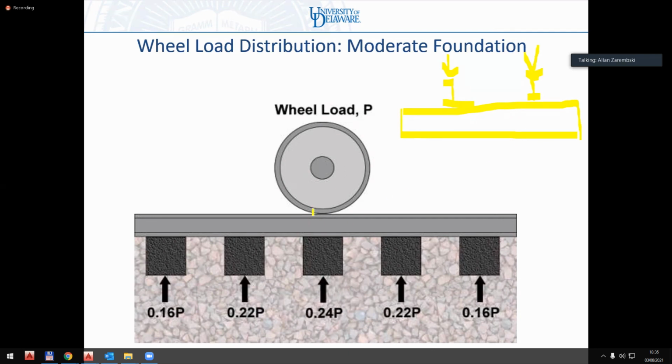But we do this analysis independently because each rail is subject only to a wheel load. So if I want to calculate the stresses in my rail, I have to use the wheel load, because the second wheel doesn't affect this rail. Or let's put it this way: this wheel over here does not affect this rail, but it affects the sleeper, the ballast, the sub-ballast, etc.